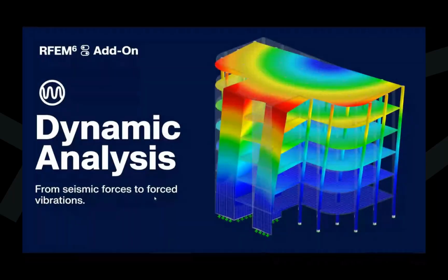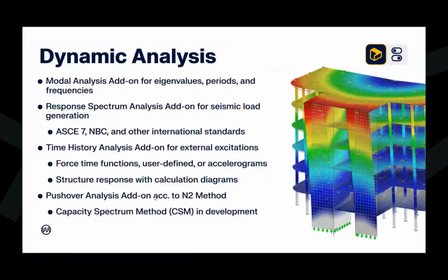Moving on to dynamic analysis. So we have several different add-ons depending on the dynamic analysis need. So everything from seismic forces to forced vibrations. So we begin with our first add-on, the modal analysis. And this will take our structure and carry out this eigenvalue analysis to determine the natural periods, frequencies, mode shapes, accelerations. This add-on is always a prerequisite before we can utilize any of the other dynamic add-ons listed here.